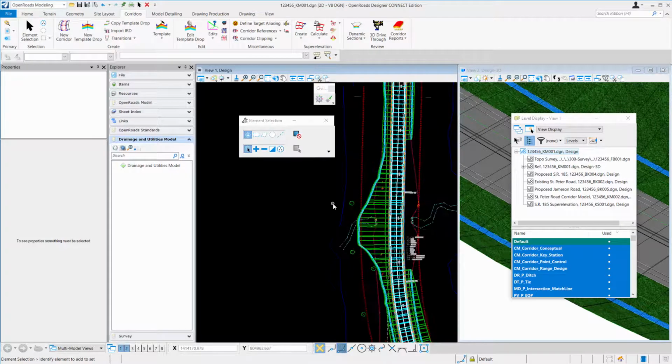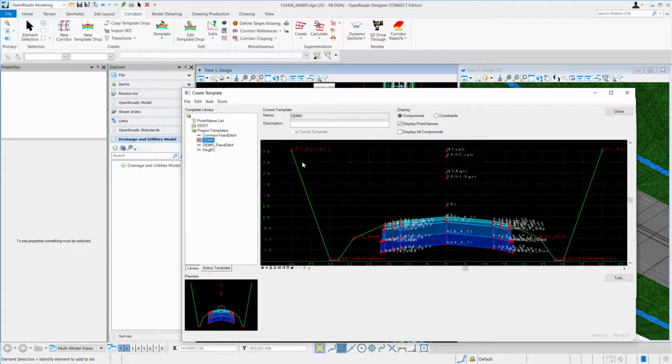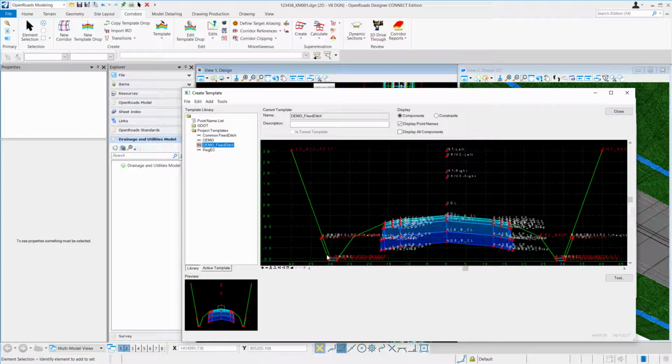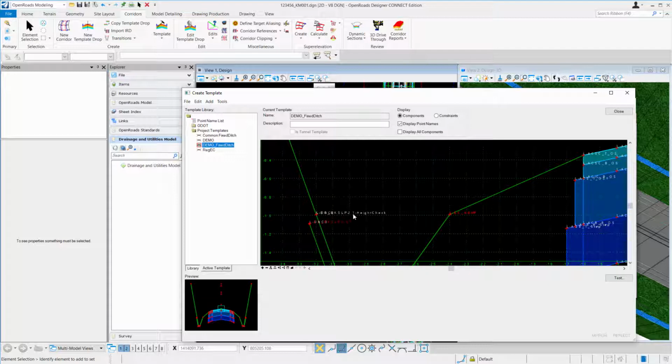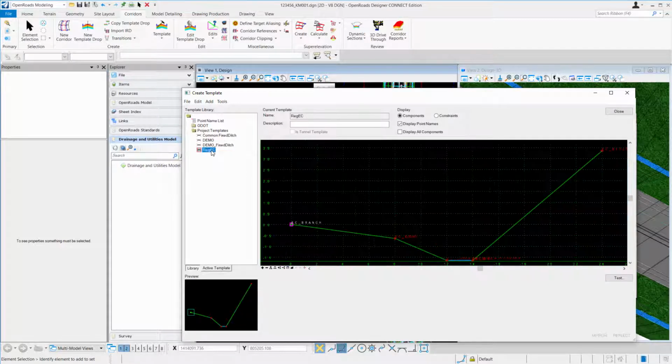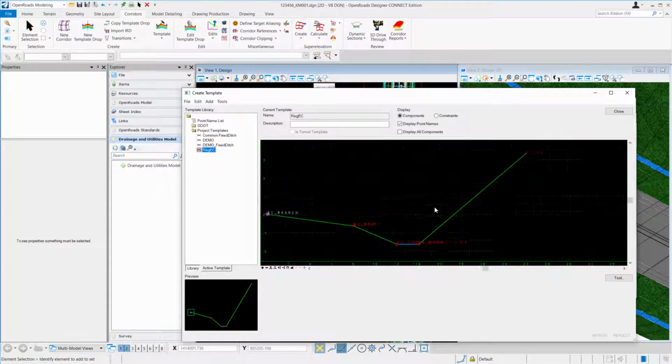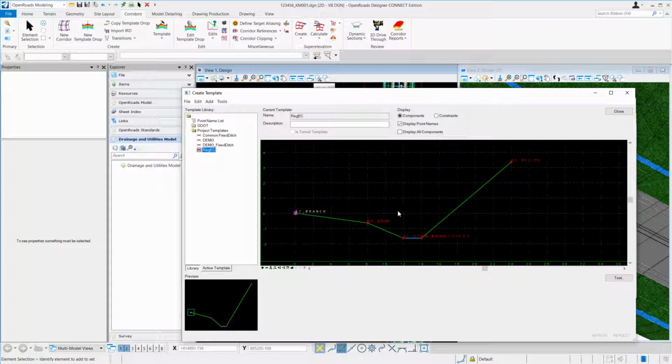Okay. So one last note while we're talking about it: my fixed ditch template did have a checkpoint, a 2-to-1 height check here, whereas my regular one didn't. So depending on what you did with your profile, if you drew something in, that height could change. So if you really wanted to make sure that you were meeting your minimum ditch requirement, you can go ahead and add that height checkpoint in, and a bunch of the templates have it.